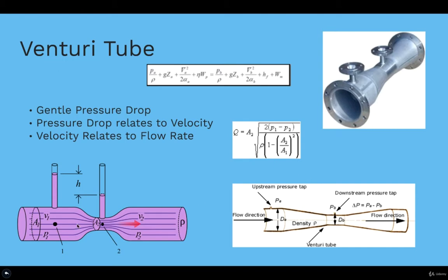Now, as you can see here, guys, you can relate the area and the diameter of area 1 with respect to area 2. Then we get this equation, the one which I was telling you about. There is no work, there is no gravity because we are assuming they are at the same height. Therefore, the only important factors are pressure and velocity at point 1, and pressure and velocity at point 2. After solving, and of course velocity, you obtain it via the relationship between areas, diameters, volumetric flow rate, and so on. You get this value right here.